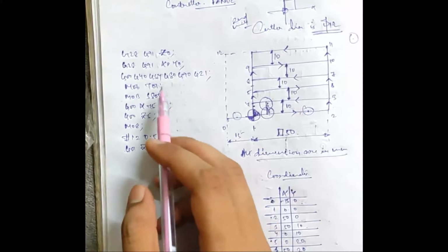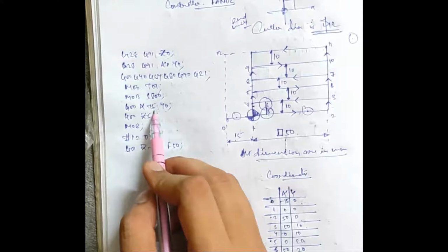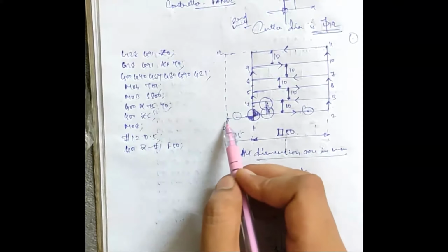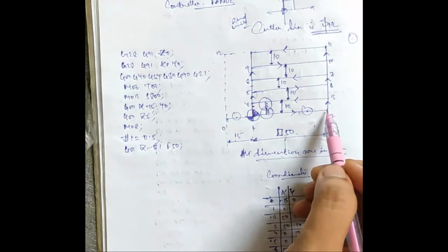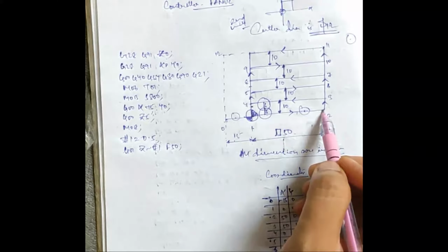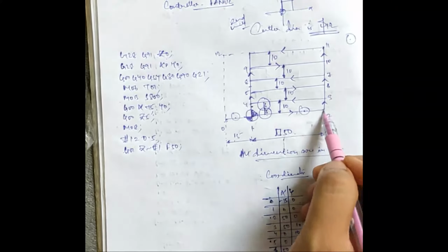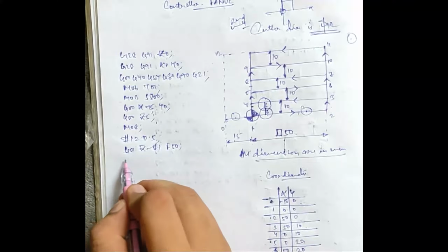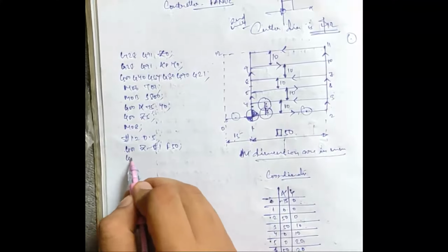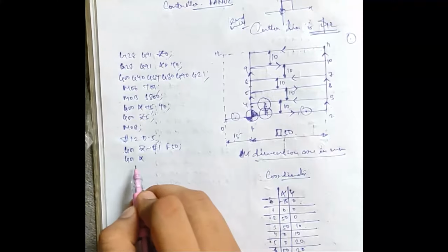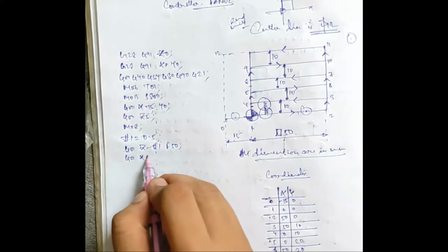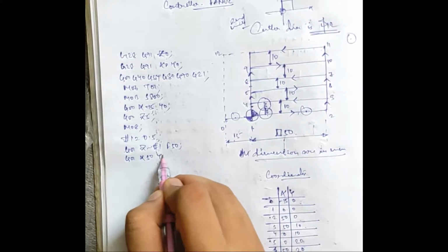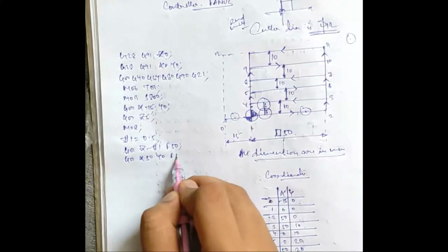Okay, after plunging at that point, which is minus 15 and y0, 0 to 1 is a straight line, then we are going to use G01 for that, and after that write the coordinate of point number 2. G01, x will be how much? At point number 2, x will be 50, y will be 0, then we will be cutting feed F500.